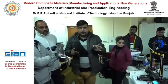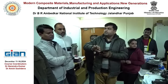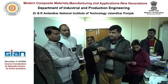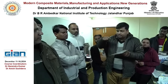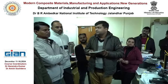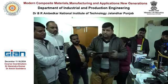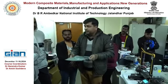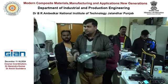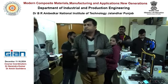Because once the part printing is completed, we need to remove the specimen from the base. So if it is not flexible, then what will happen? The first layer is stuck with the platform, and it will be very difficult to remove that base layer. It will damage the part also. It will damage the printed specimen. So now what we do? We just take out this print bed in our hand and bend it like this, and then automatically that layer is removed, and we can easily remove the specimen from the print bed. So this is, I think, one of the advantages.